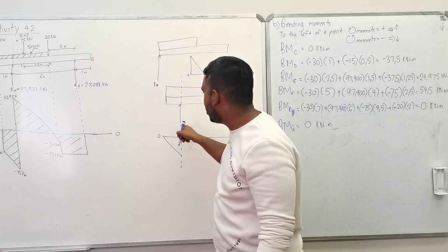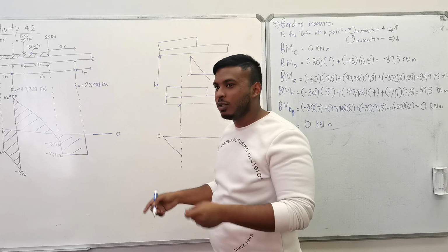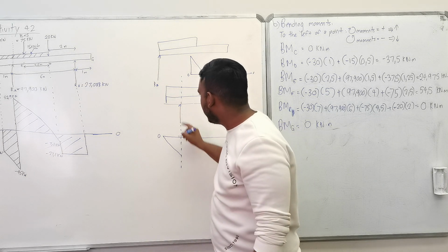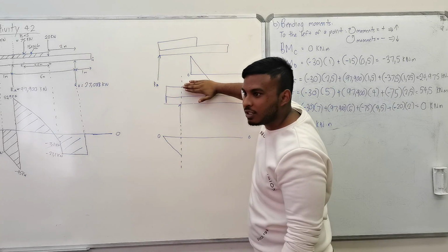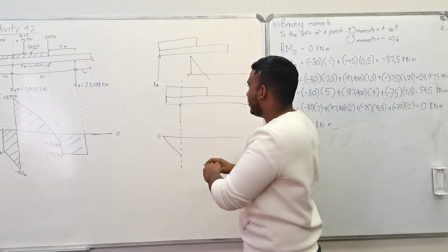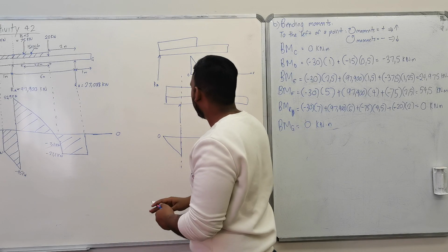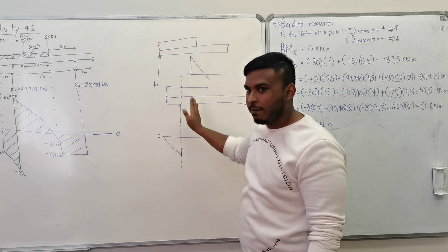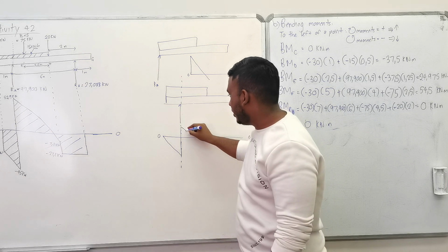But with the introduction of the support, which is a concentrated load, and concentrated loads are vertical lines, you're going to have to basically cut this portion. So you basically ignore the rest of the distributed load. You'll work out that force, you'll show it. When you come onto the other side, this here would create maybe some form of support. When you come onto this side, you would cut the load again, and you would do your calculation again.